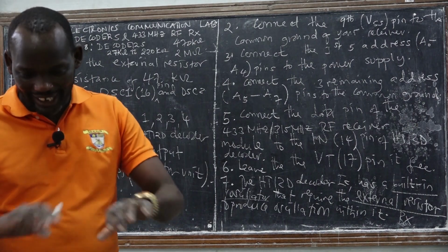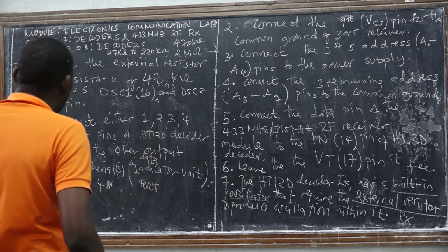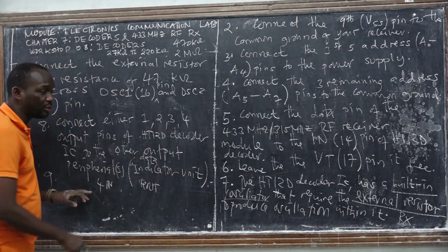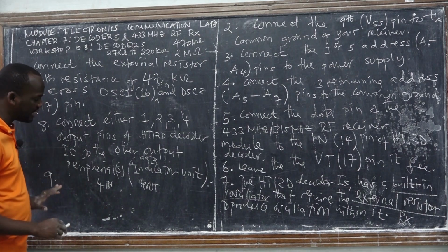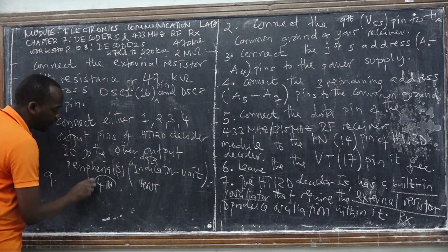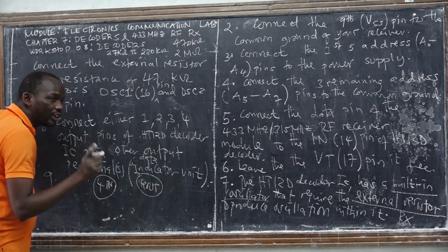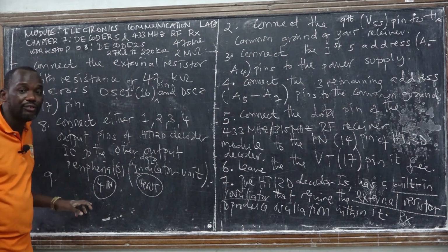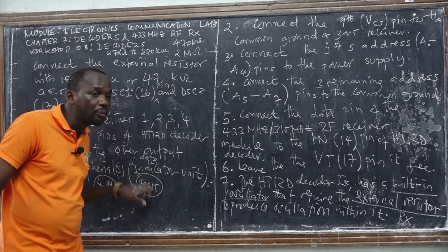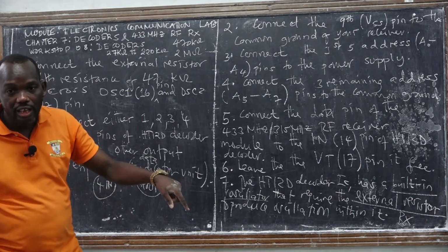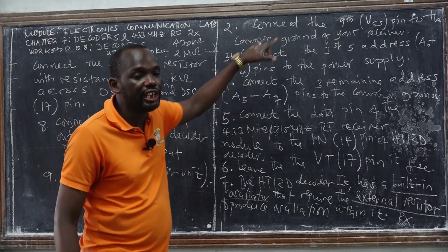Just ignore what I say. But one thing I want to tell you, the goodness of electronics and telecommunications engineering: we are not limited with the 4 inputs of the encoder. Also, we are not limited with the 4 outputs of the decoder. We can have more than 4 inputs of the encoder, and more than 4 outputs of the decoder, within this HT12D decoder and HT12E encoder.